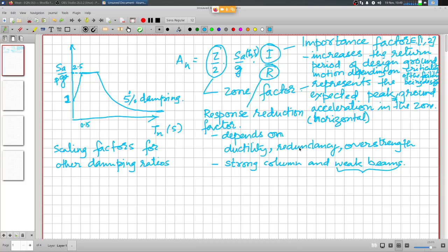So ductility is important. Now, what is the implication? What do you mean by ductility? I have already mentioned the importance of confinement. Confined concrete is essential, because unconfined concrete will only give you an ultimate strain of 0.003 or 0.0035, around that value, right?